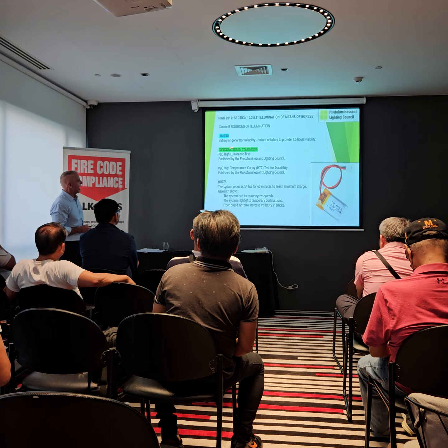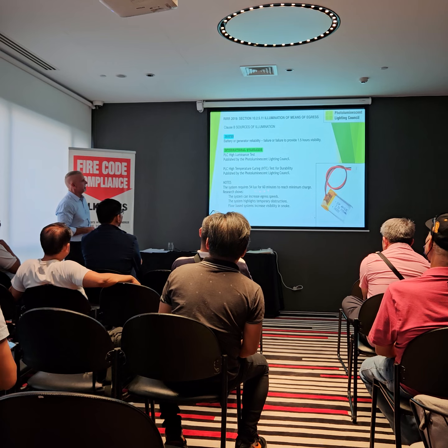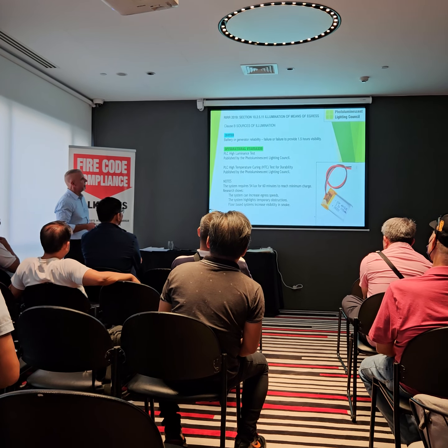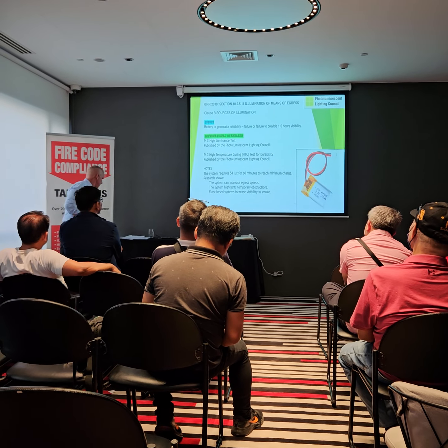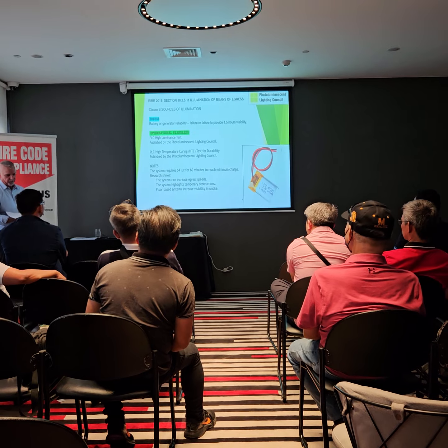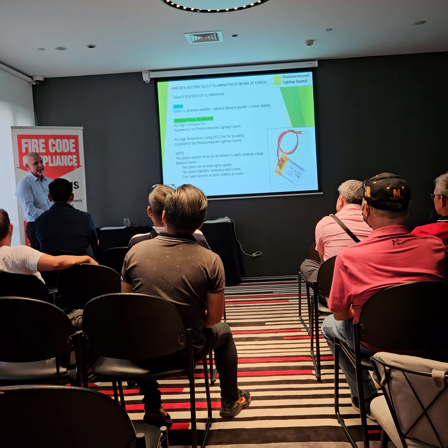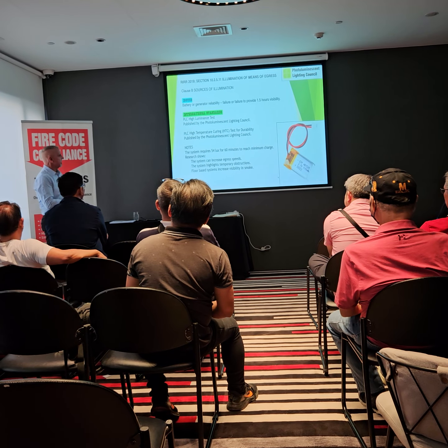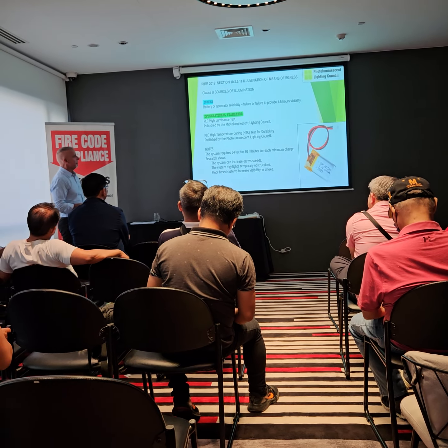Again, same standards here. You need 54 lux, 60 minutes to reach the minimum charge. Now, with these systems, and we've included all the research with this guidance document of all the studies that support these claims, egress speeds increase if you have photoluminescent material. Systems also highlight temporary obstructions.